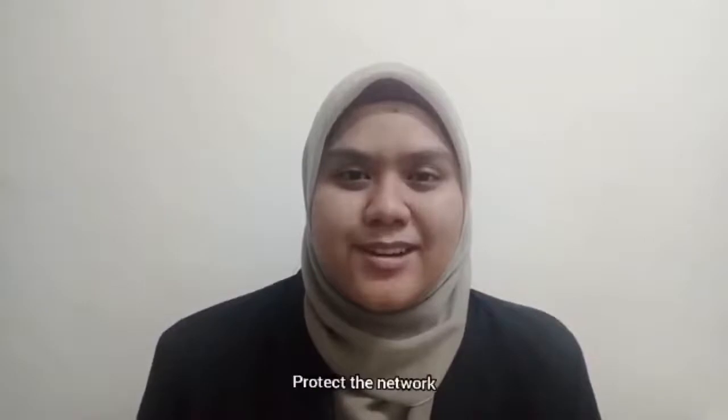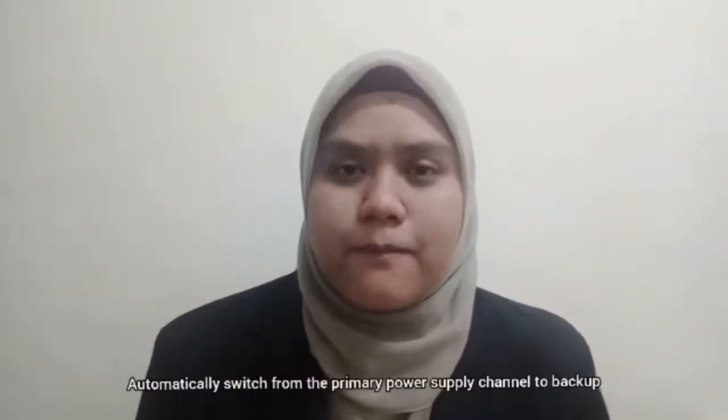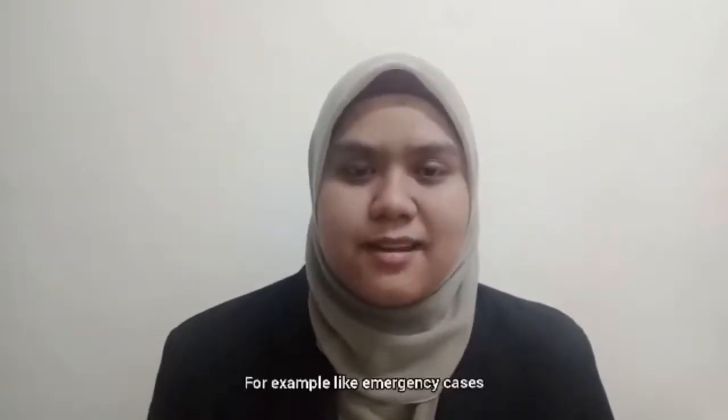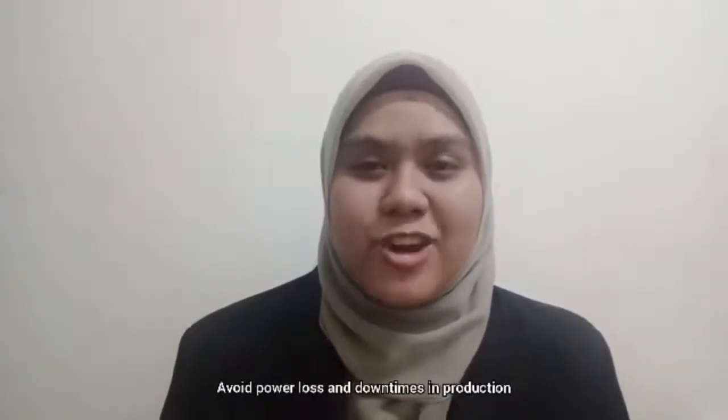I'm going to present about the main switchboard. So what is MSB? MSB is an assembled unit of electrotechnical components. It is used for receiving, measuring and distribution of electrical energy and also protects the network. MSB is also an equipment that automatically switches from primary power supply channel to backup in case of problems with the supply of electricity, such as emergency cases. MSB is an important and responsible part of the electricity network as it helps to avoid power loss and downtime in production.